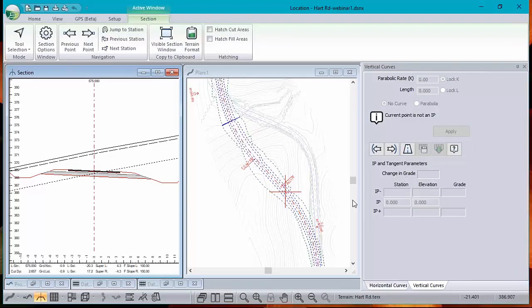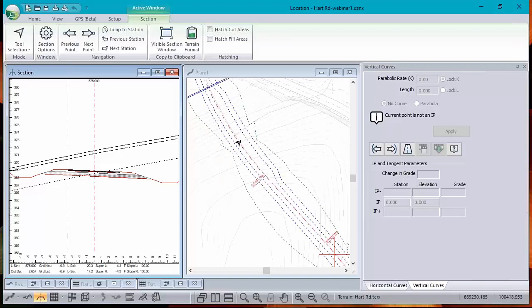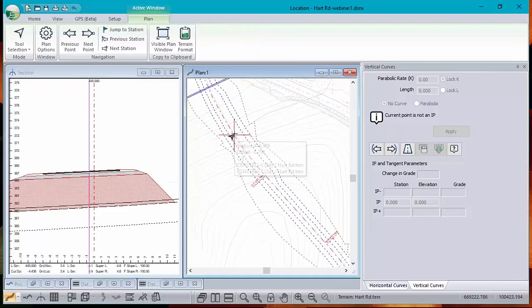So in this one, I actually noticed that there's a widening here because there's a driveway coming in, and so we've got a kind of a turning lane here. You see the roadway here is symmetric, same width on each side because I'm at this cross section. And as soon as I click over here in the widened area, you can see it's wider on the left. I'm also in a curve, so I got super elevation.